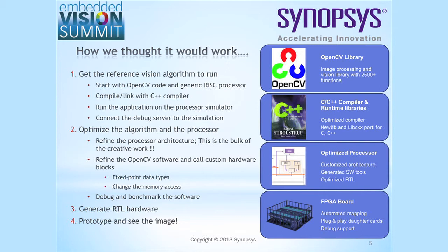Okay, now the fun starts, and this is the heroic stuff. We're doing supercomputer design by optimizing the vision algorithm and the coprocessor that goes into the hardware. This is work where you do spreadsheet based optimizations on, do you have the memory bandwidth? Will you have the actual memory bandwidth through the pins of an FPGA? Build custom operations, and then, of course, following the book by Hennessy and Patterson, the dogma is if you build something custom with instructions, you need to have the memory path to it, otherwise forget about the performance. So this is the cool stuff.